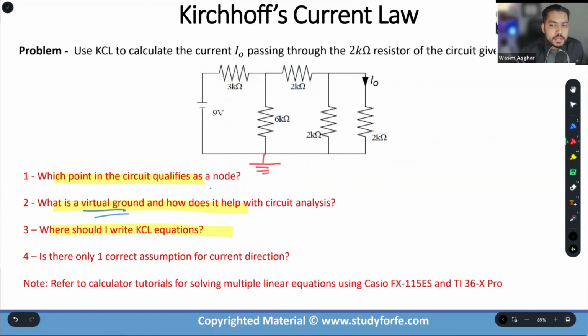So is there a need to write a KCL over here, a KCL over here, a KCL over here, a KCL over here, at all of these 4 blue dots? Well, the first answer is that all of them are the same node, the same point. So even if you want to write an equation, that equation should just be written for one of these nodes. And since they're the same voltages, you're done with that. Makes sense? Because it's a common reference point. And then the next question is, is it an unknown voltage? Because KCL should be written at nodes where the voltages are unknown.